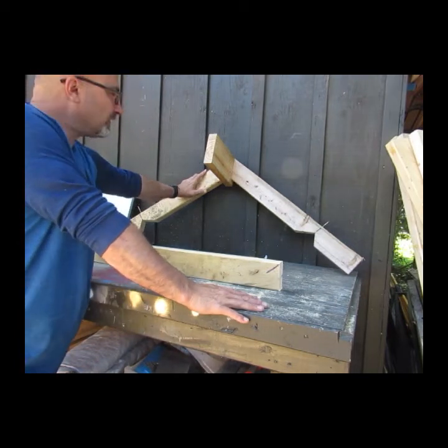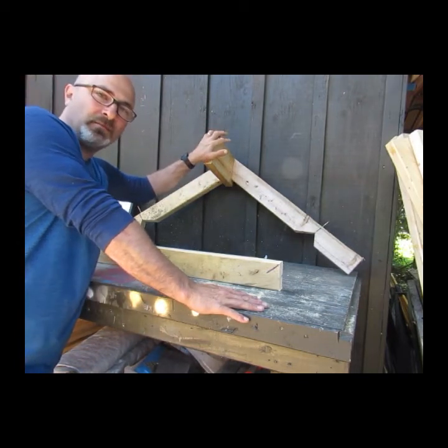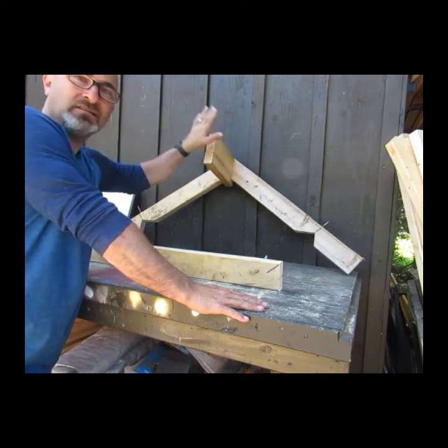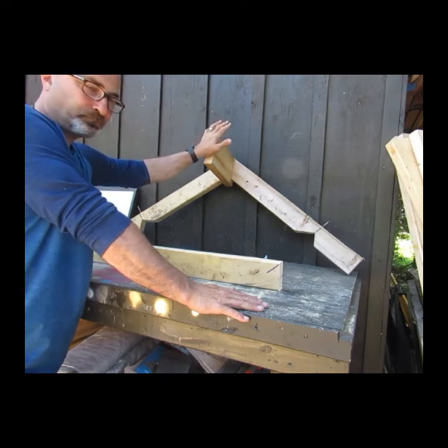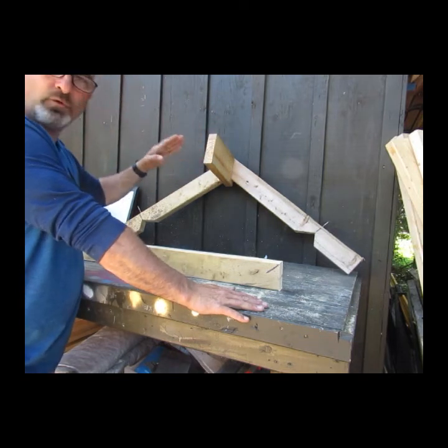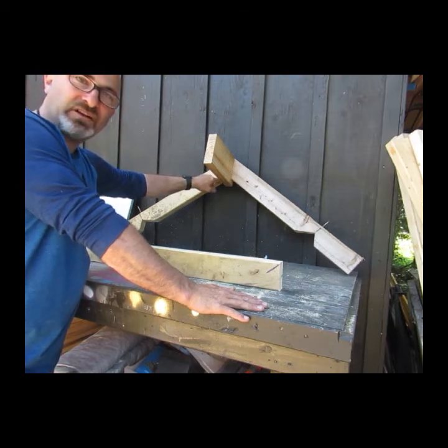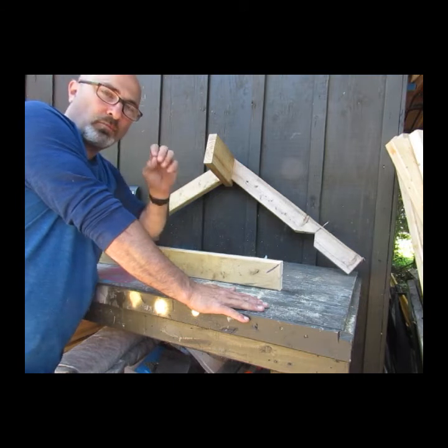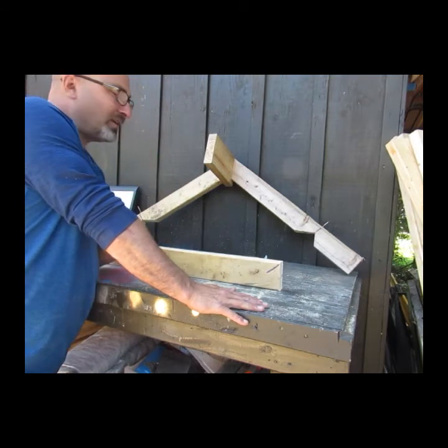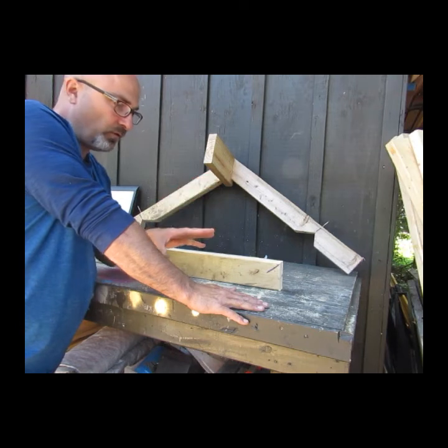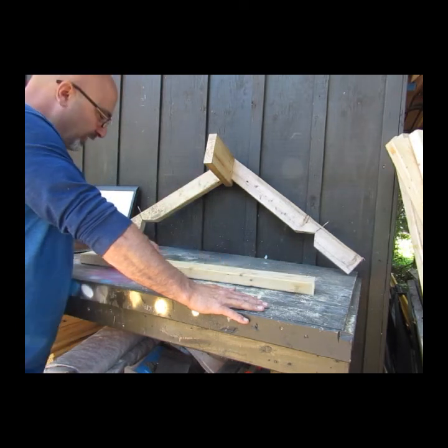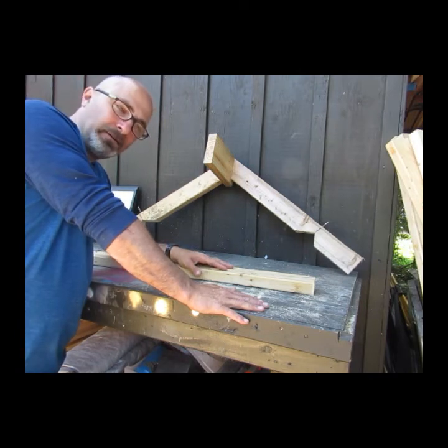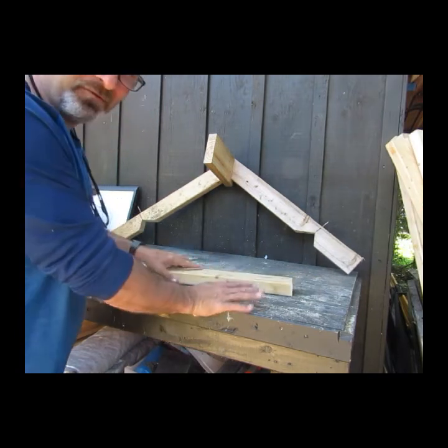What you would do, like I said before, is support this ridge beam, level it, and put it in the right spot where it's going to go on the far ends of your roof. You would support it, and then you would start laying all of your rafters, with the angles cut and the bird's mouths cut, all patterned after your first piece, your pattern piece. So you cut your first one, make it perfect, notch it out, do the whole thing, and then you just lay it on top, cut, cut, cut, tracing and cutting, tracing and cutting. That's what apprentices would be doing.